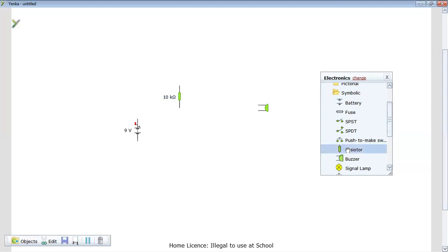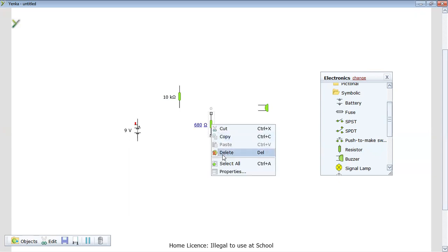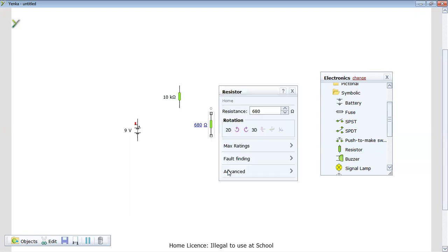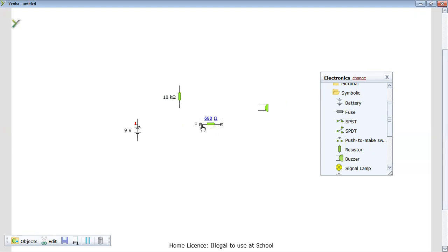That's my first resistor. And this is a handy bit to know. Second resistor, I want to bring in here, but you'll notice my second resistor is actually sideways. Again, I can change that by right-clicking, going to properties, and I can just rotate it. And there we go, like so. So again, this one here, what's the number there? I've got 1K, 1,000. So 1,000 ohms. And as I click off of it, it will change it to 1K there. Now, those two are connected together. This one up here is connected down to my battery.